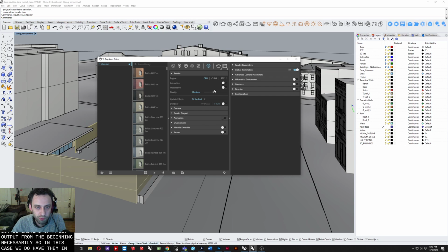So in general, when testing, I tend to leave it at medium. When going for a sort of final production render, I tend to go high. Beyond high, high plus, you get sort of diminishing returns. So if you're really concerned about light quality, like if you're in a space where it's really limited on light, going up to high plus or high will probably have a bigger impact.